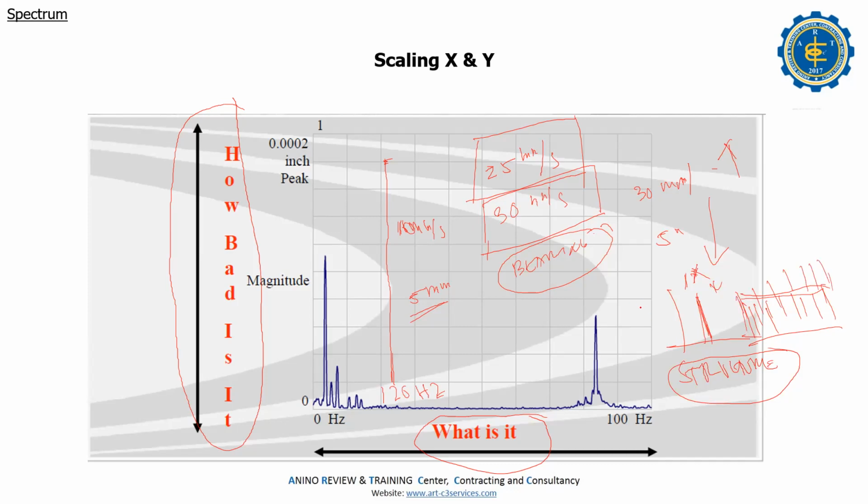Sometimes the maintenance did not grease the bearing, because to grease the fan you will climb, right? The maintenance will not climb again for greasing. See, in Saudi Arabia, climb again, Sadiq. So sometimes if you encounter this one and then the bearing frequencies, order the maintenance to grease. After grease, then you take reading, then the vibration goes down.